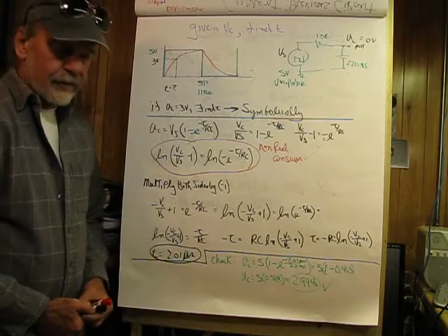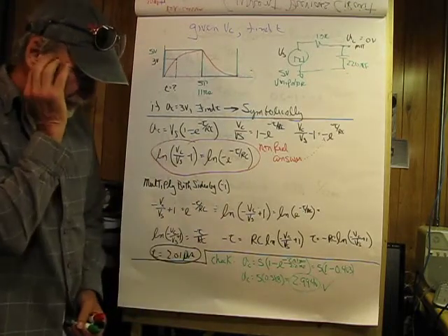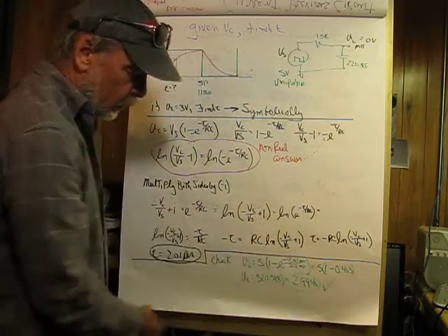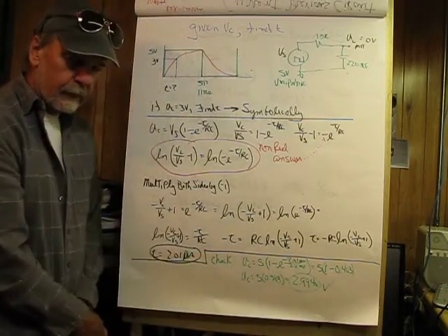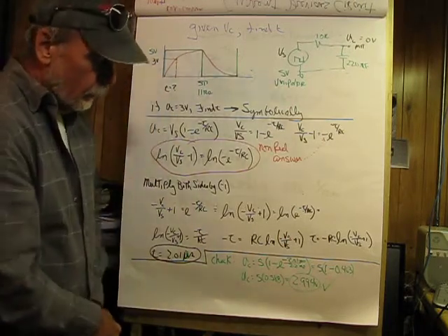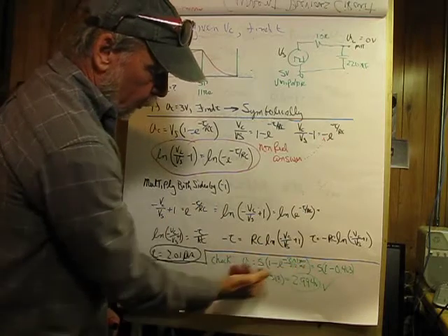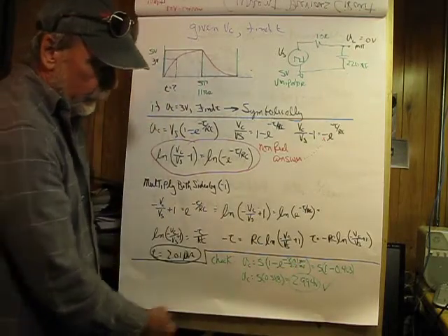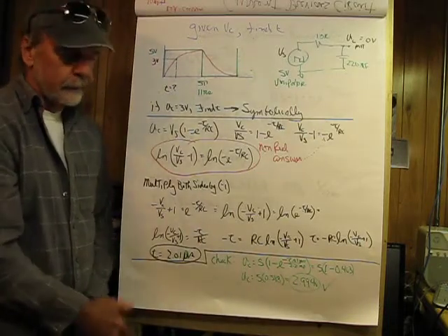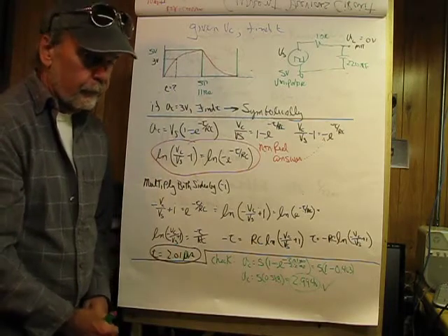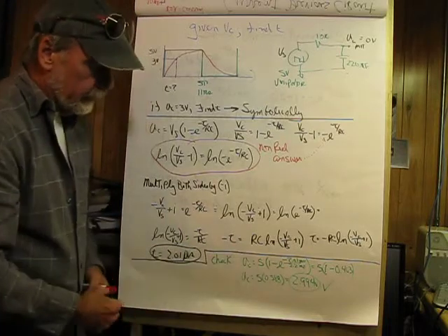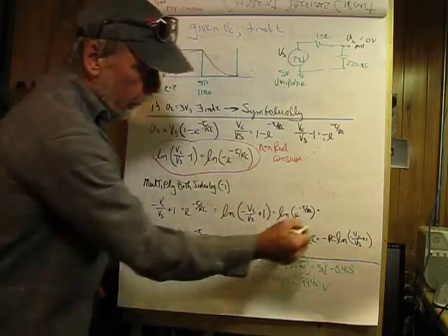And I kind of want to check this. Work through all these numbers and stuff. It's good to check things. So what I'm going to do is substitute the t I got into the equation, solve for VC, and if everything goes well, it ought to come out to be 3 volts. So in doing that, using the standard formula that we've been using a while, and doing the math on this, my calculator pulls up 2.994 volts, which is good enough, 3 volts. So I'm fairly confident that the solution to the problem of finding t would then be this equation symbolically.